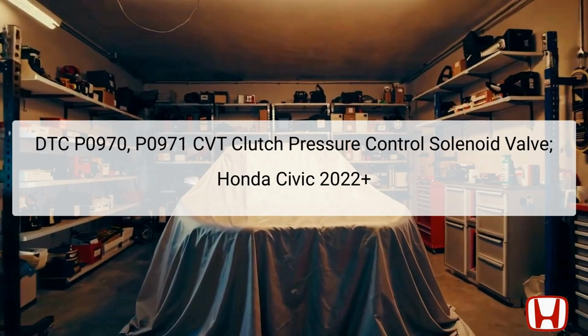The CVT clutch pressure control solenoid valve is crucial for controlling the pressure applied to the clutch in the continuously variable transmission, CVT, system, facilitating smooth gear transitions. The location of this component is integrated within the valve body assembly, which is situated in the transmission housing. Understanding these codes is vital for diagnosing transmission issues effectively and restoring optimal vehicle performance.